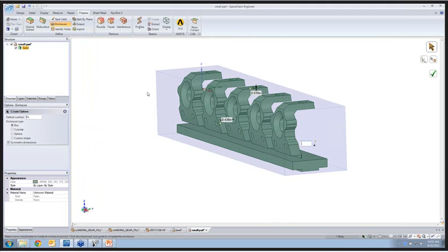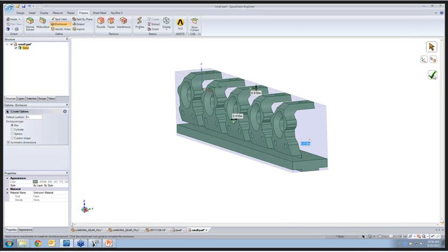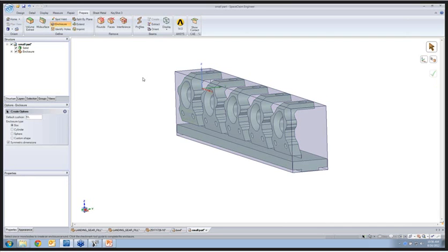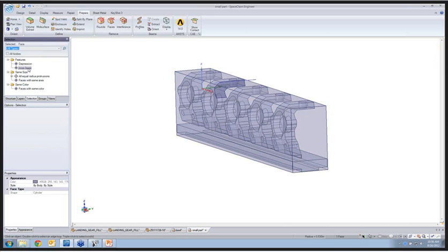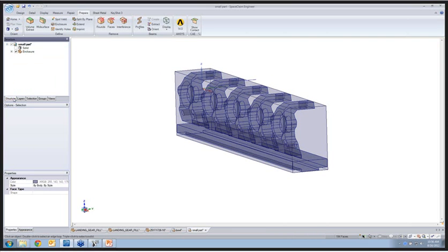And I could dictate the offset, the clearance between the enclosure and the body that I have in front of me, namely those 5 parts all connected into one. So there's my enclosure. It's a fast way to get a block on the screen. Now, the only issue is that it is, in fact, an enclosure, and it does have a hollowed out core, which I don't want. I want to get rid of all those faces on the inside of this. I have a way to do that.